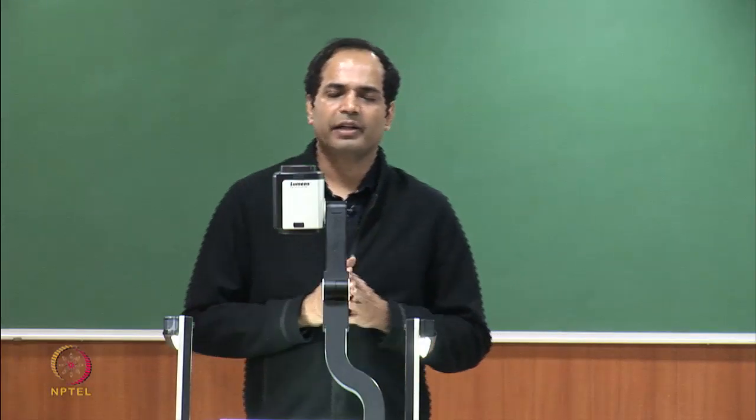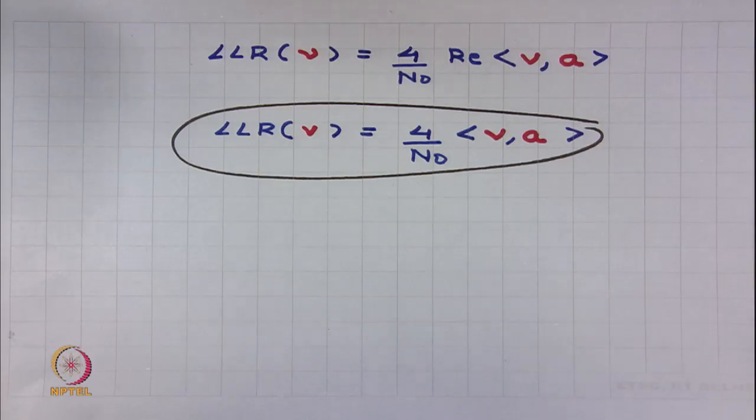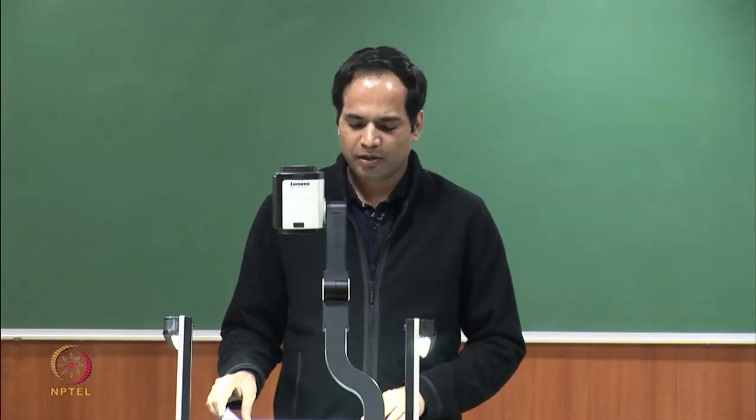So, previously we said that log likelihood ratio is a sufficient statistic, because just by looking at log likelihood ratio your detector can decide for the hypothesis, and this is a great saving in this case, because you might have a bunch of numbers and you can convert this bunch of numbers into a single number by carrying out this operation, and by looking at that single number you can decide for the hypothesis.